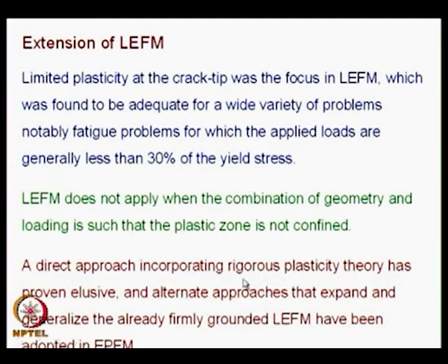in those approaches what you really want to do is, you have already learnt concepts related to linear elastic fracture mechanics, how these concepts could be modified and adapted for elastoplastic fracture mechanics. So, what you will find is, like we have looked at energy release rate, we will also look at energy release rate, and we have looked at R curve, we will also look at J curve here.